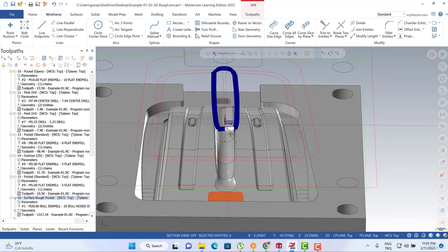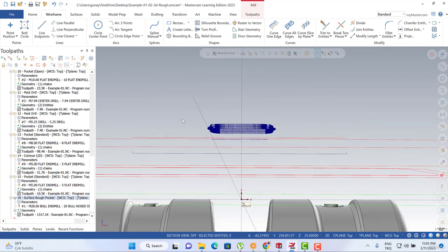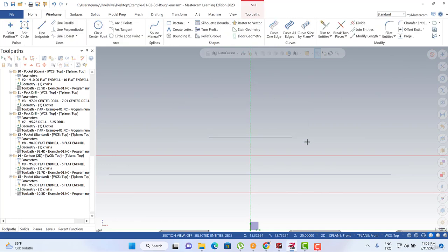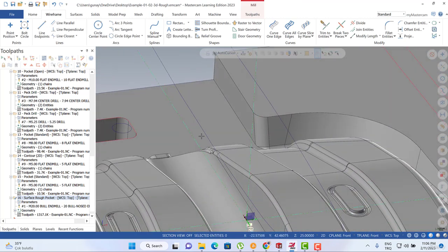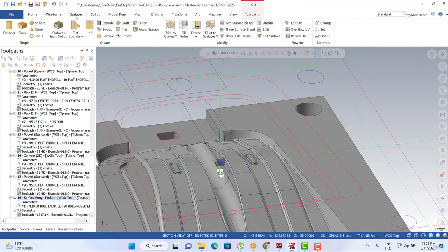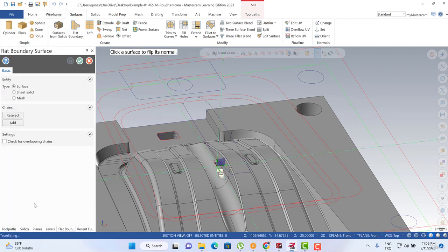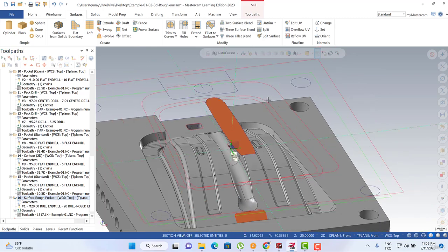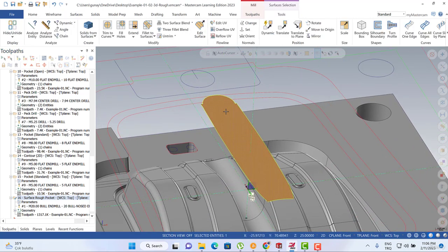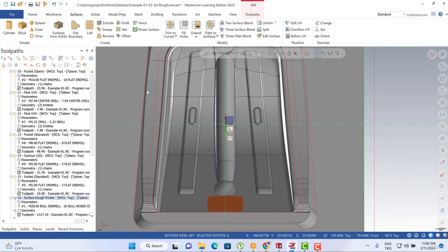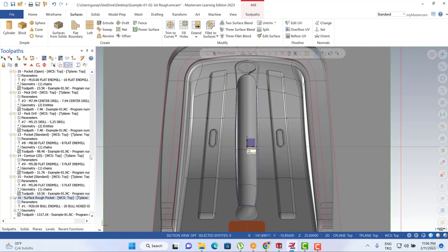And after that, actually, we can also turn back to the front view here, and we can hit here, select the only point option, and then we're going to create our window, and then we can delete all the points. And after that, when we turn to the flat face and select our boundary, it's going to create it automatically like this. So this is the best way to create your boundary, actually.